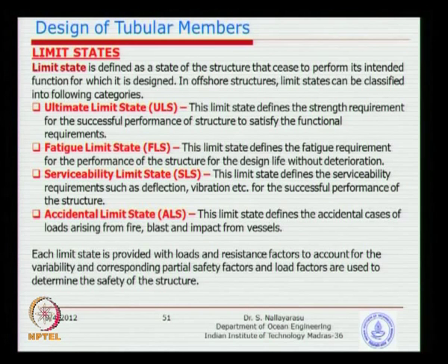In LRFD or limit state design, we have to define several limit states. What is the meaning of limit state? A limit state is nothing but a state of the structure or system unable to perform the intended function. For example, you design a beam for carrying a load by bending, and it is unable to satisfy the bending strength, then that state is called a limit state, a state at which the function is unable to perform. Of course, other functions may actually perform. For example, a beam may be very safe in strength but unsafe in deflection. That means its limit state of deflection has been reached.